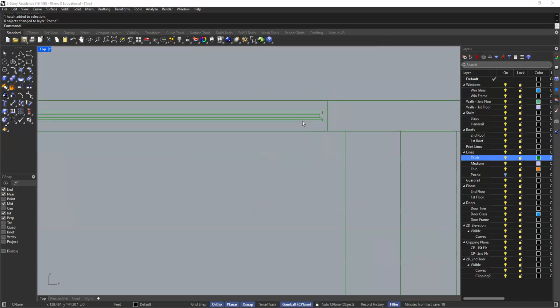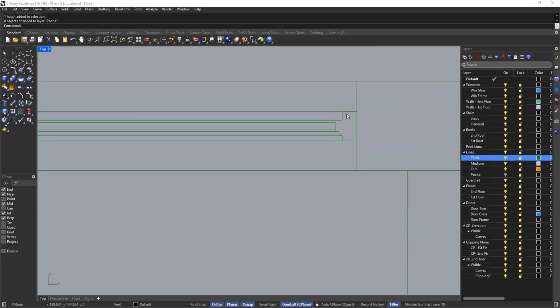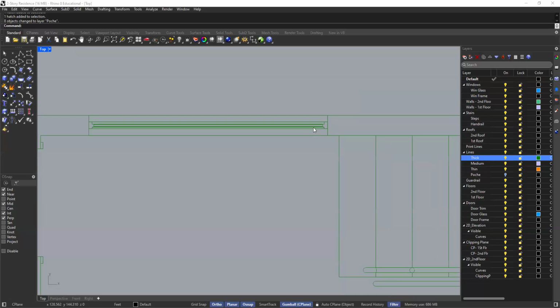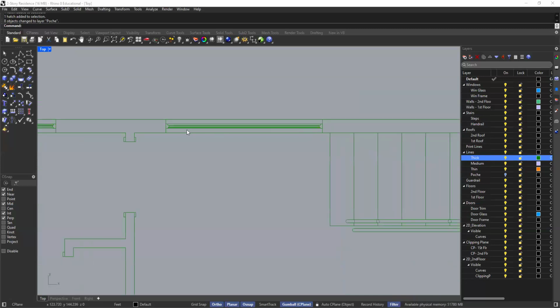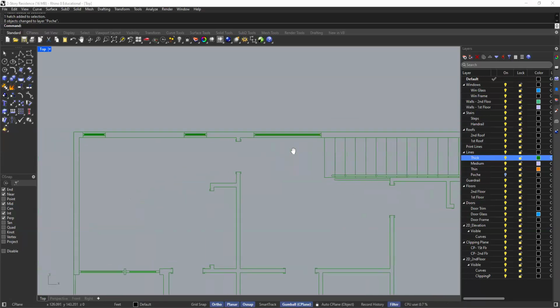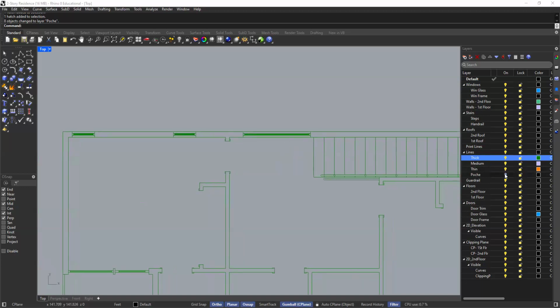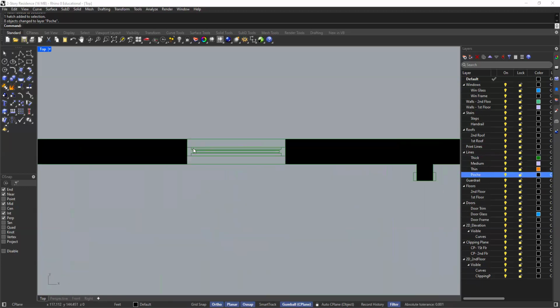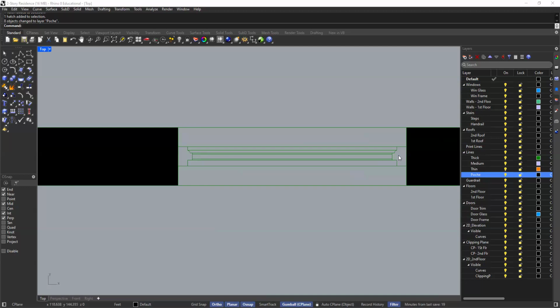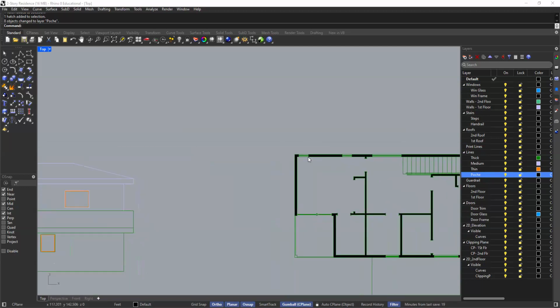The first thing that I want to address are these windows. Now, technically these windows I'm cutting through. Actually, I am cutting through them. So we need to actually poche those. I didn't realize that. All right, so let me bring the poche back. We're actually cutting through these window frames. So we actually need to poche through those window frames.